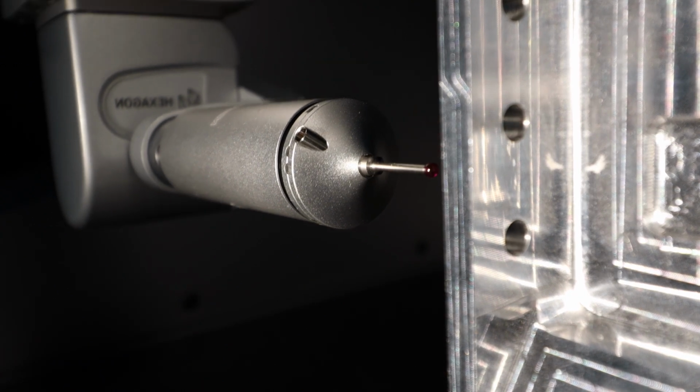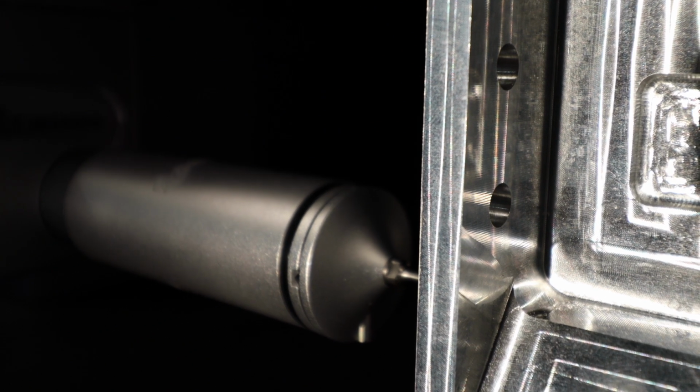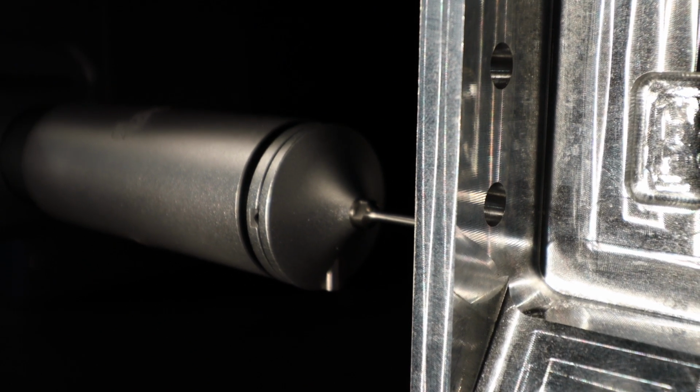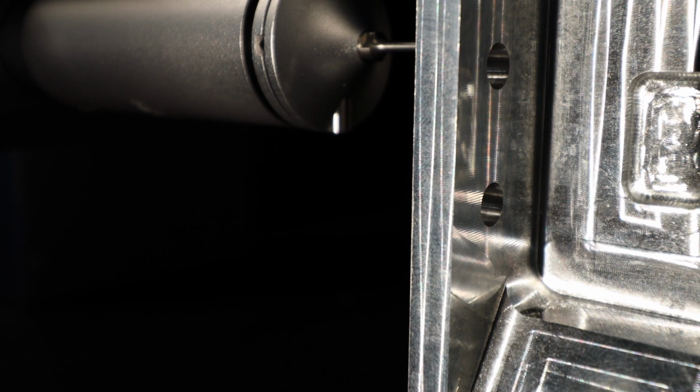This was going through the steps of actually setting up the strategies. Thank you so much for walking us through how to set up Siemens to be able to automatically program our CMM. With that, you can really see the value in being able to leverage model-based definition to automatically program your CMM. It doesn't take much to set up the strategies, and now a technician can just simply file, import a model-based data type, click a few buttons, and generate an entire CMM program. This saves a lot of time and has an immediate impact on your manufacturing processes.